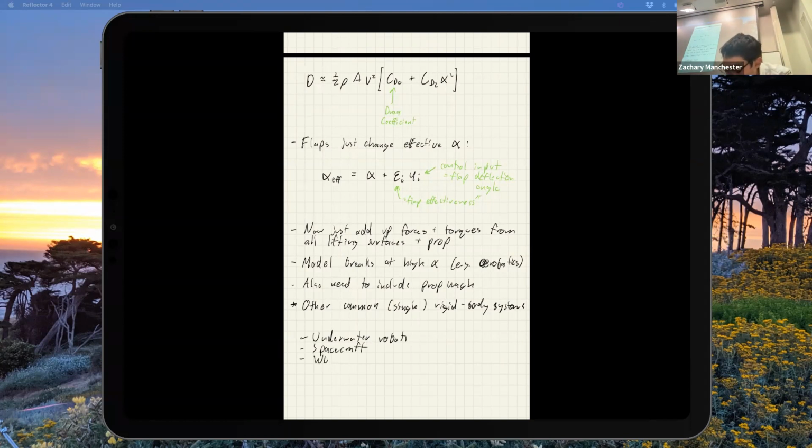And legged robots are also super commonly modeled using what are called centroidal dynamics, where you assume all the limbs are massless and just model the center of mass with rigid body dynamics, and it looks like this also. So most legged robot controllers also have these dynamics in them.